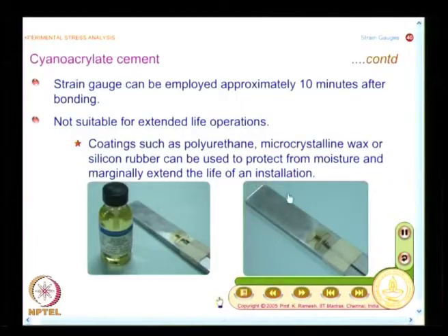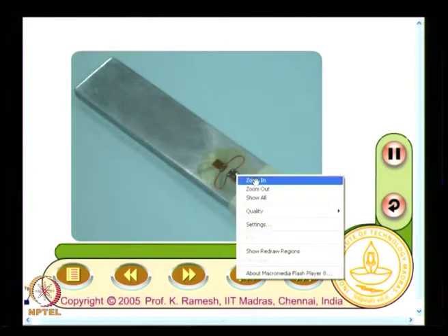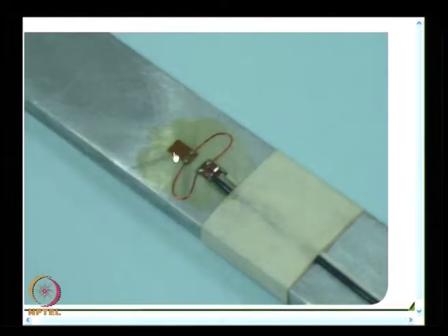And the example you see here is also good. You have a nice strain gauge installation, where I have a strain gauge. These are connected by a thin special type of wire, and these are all the connectors. It is easy for soldering, and this is the lead wire, and the lead wire is also anchored.